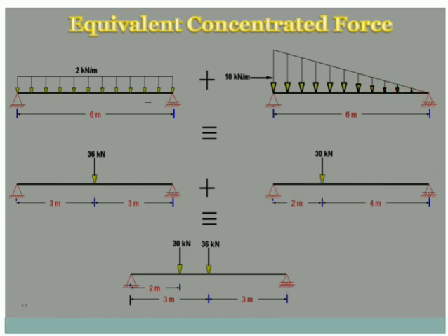So finally, what diagram do we have to use for analysis? The total representation is here. This 30 is the UVL triangular shape, this 36 is the UDL, which is rectangle shape. So one UVL of trapezoidal cross section can be represented as 2 point loads as shown in this figure.